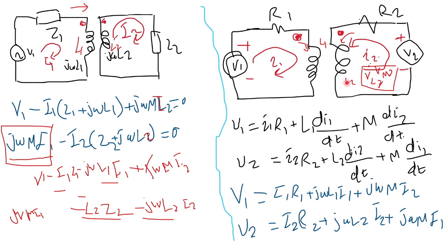Now for the mutually induced voltage, since this is an aiding connection, both mutually induced and self-induced will have the same sign, same polarity. So the voltage around L1, because of the mutual inductance, because of I2, would be a voltage drop as well. So it has to be written as plus M dI2 by dt. It has the same sign as the self-induced L1 dI1 by dt voltage.